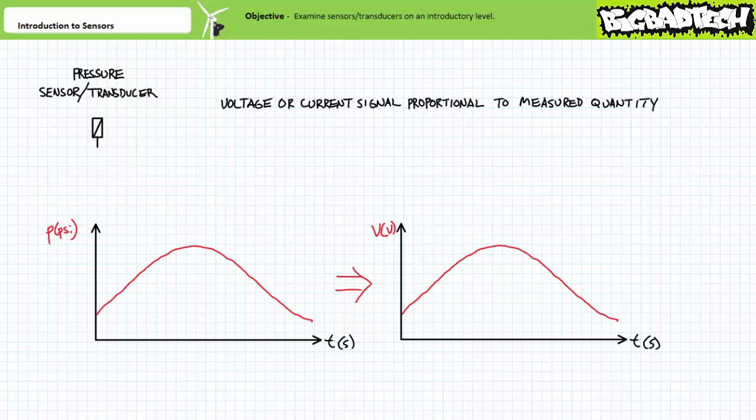The schematic symbol for a sensor is pretty bland. Most sensors, regardless of type, are depicted as a box with a diagonal slash through it. Key to the operation of a sensor or transducer, as the name implies, is the process of transduction. Transduction is just a fancy title for the conversion of some physical phenomenon, like pressure, temperature, rotational speed, or position, into an electrical output. Transduction means vary depending upon the quantity being measured. A transduction mechanism for our example pressure sensor might be a pressure-sensitive plate that, when increasingly displaced or distorted by increasing pressure, produces an increasing voltage output.